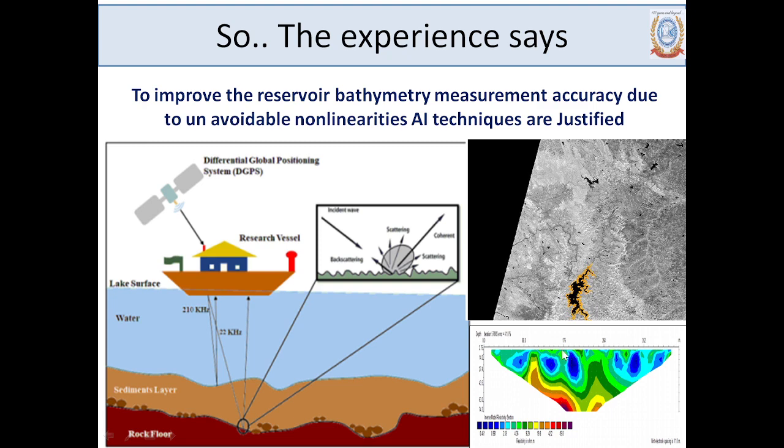So now you have to teach your machine what material this resistivity index corresponds to, and what this one corresponds to. If you can see the alignment, the resistivity index has been mapped very nicely. So this is the way the bottom profile is expected to be. The only thing is we don't know what it is, but we know the resistivity index. Now when you feed it and call this marble, or this rock, or this iron, then the system will again classify it accordingly.